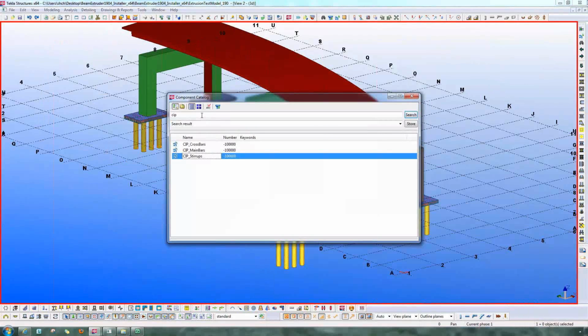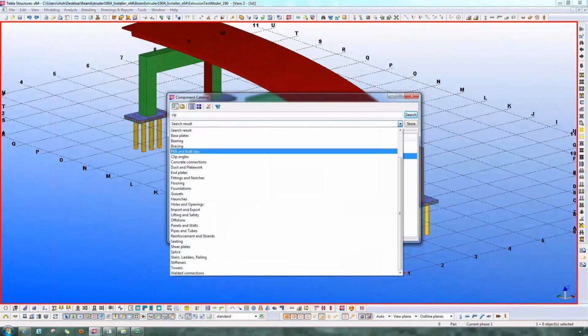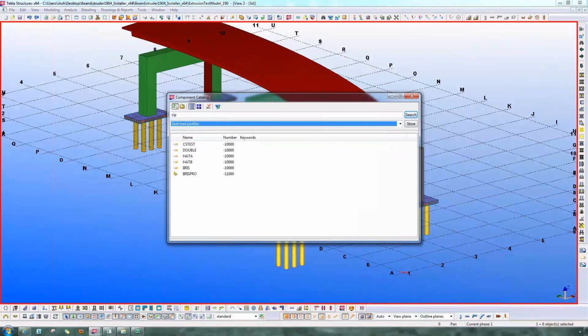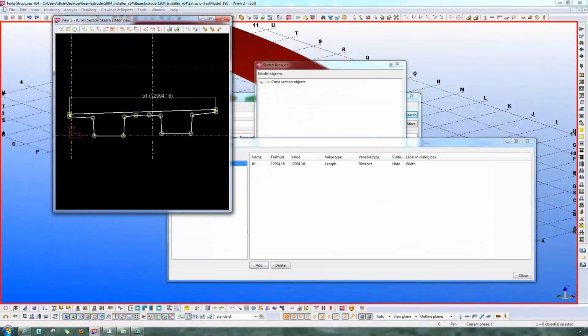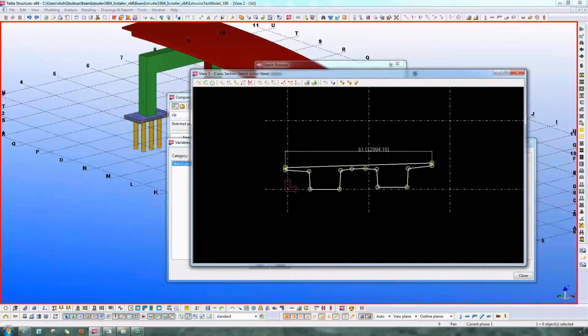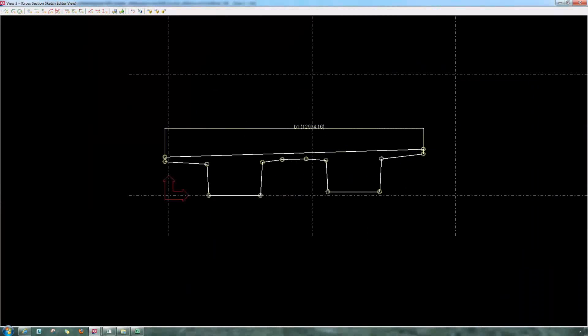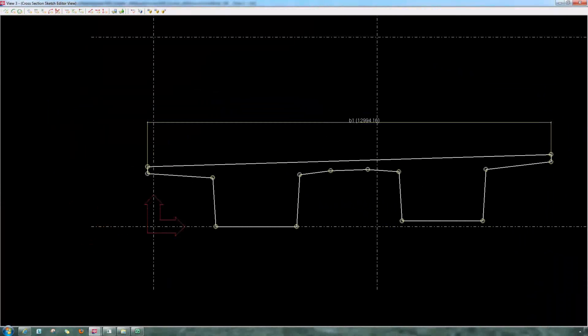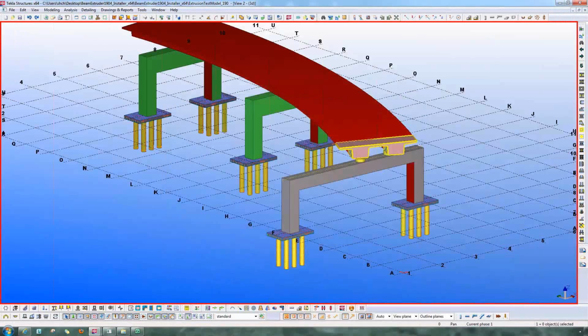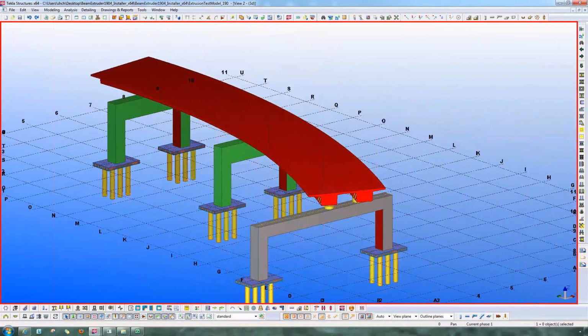If I go to the custom component catalog, there is a library, and here we have some sketch profiles, and if I select one of the profiles, what I used just now, it is with the proper slope, and this is a user defined one, so the user can change, and he can create it as a parametric one even with some openings, that is possible. So basically working in the curved portion is faster and easier in Tekla Structures.